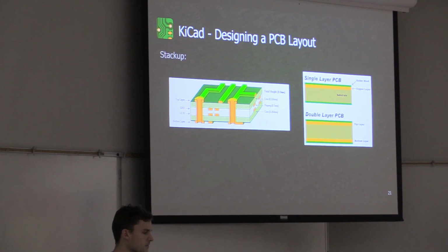In our case, we're using double layer PCBs, so this figure on the right here explains it better, where we've got our main substrate and then the copper layer, and then of course sometimes, or most times, you'd have a silk screen on top and a solder mask on top to keep the copper from corroding, keep solder from running across all the other traces and so on.